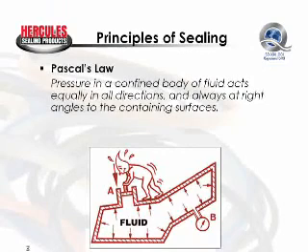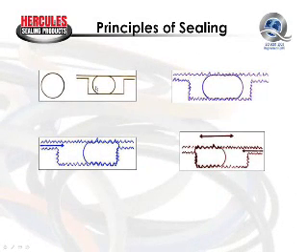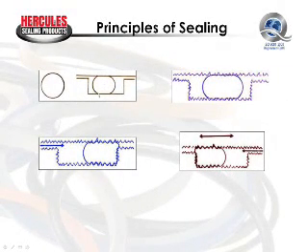Okay, now, here we see an illustration of an O-ring in its free state. Here's the O-ring after it's been installed in the groove, in the gland. You can see how the O-ring is being compressed radially and how it changes shape axially. By compressing the O-ring radially, we're improving the conformity to the sealing surface into which the O-ring is coming in contact.